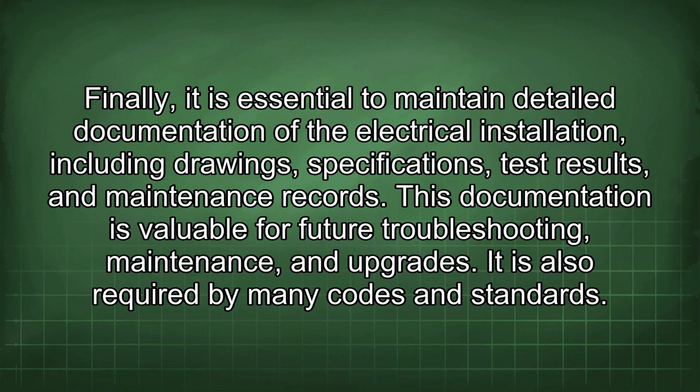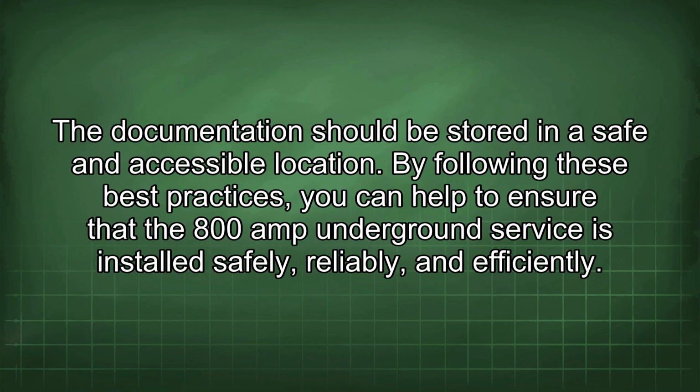Finally, it is essential to maintain detailed documentation of the electrical installation, including drawings, specifications, test results, and maintenance records. This documentation is valuable for future troubleshooting, maintenance, and upgrades. It is also required by many codes and standards. The documentation should be stored in a safe and accessible location.